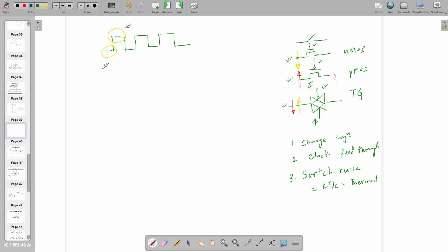That is what is connected here. Similarly, what you want to transfer is also some fixed value which is known to you. If this is ground, if this is VDD, no problem. If this is a full swing sine wave, no problem. But the problem is the resistance of any switch. How much is it if it is NMOS?